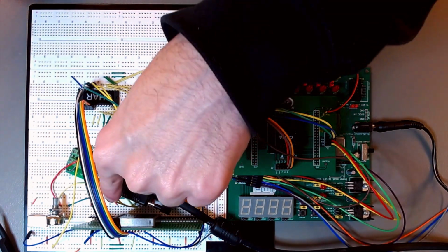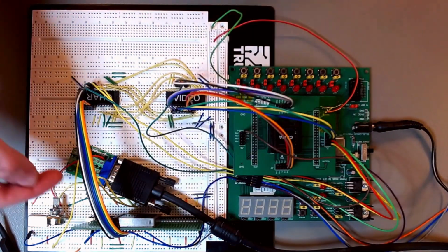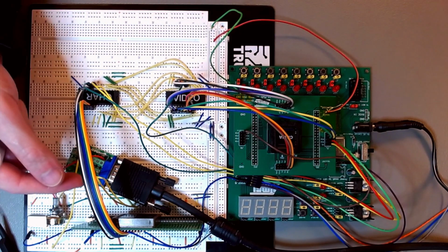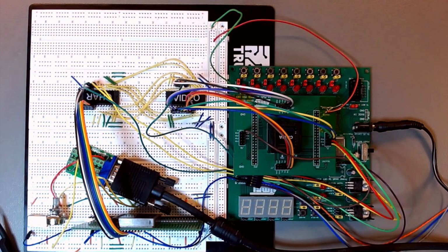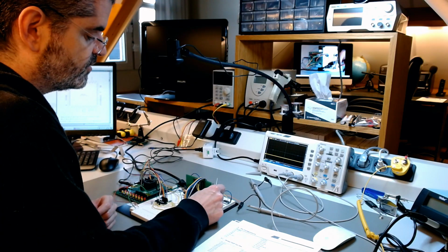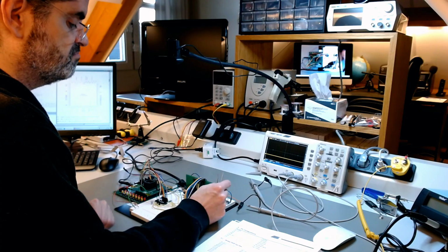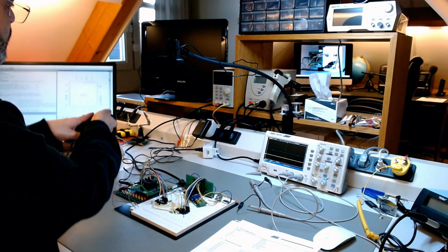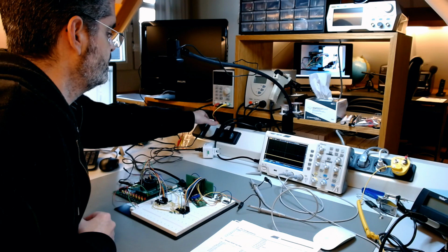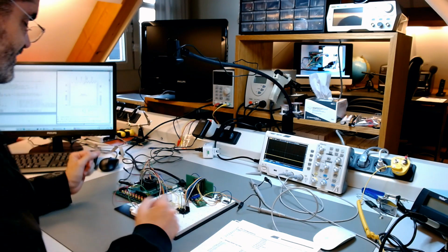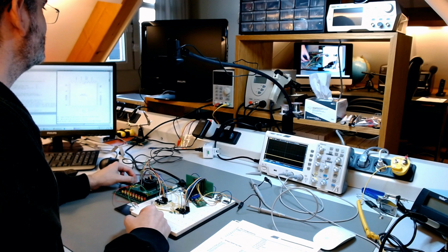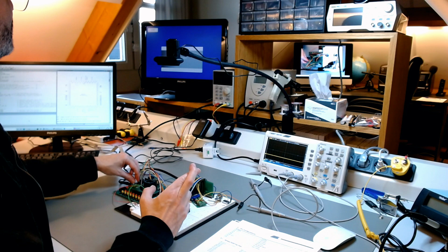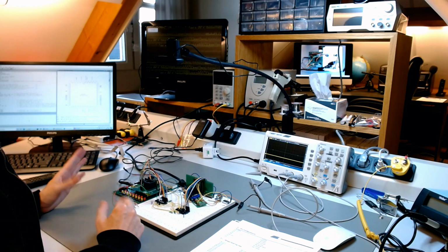These 2 wires here are the vertical sync and the horizontal sync that go into the VGA connector there, and the last wire into the VGA connector is just the common ground, which is connected here to the breadboard. I've set this potentiometer at more or less middle value, so we can start testing. At this point there is nothing more to do but to turn it on and hope for the best. There we are. Fingers crossed. 3, 2, 1. Oh, there is a sync. Yeah.